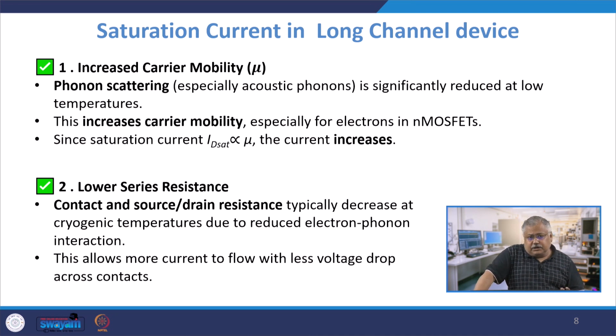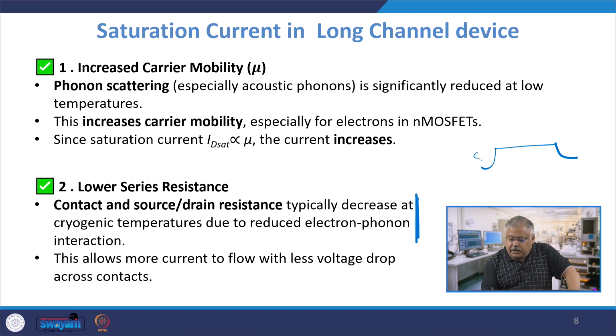Now what happens, and this is quite interesting, maybe we are discussing this for the first time. Look at the first point. If you look at the structure of any MOS device, you have source and drain here. However, there are metal contacts, which are sort of buried contacts within the source and drain, and these have contact layer metal lines which carry to the layer 1 or layer 2 level of interconnect.